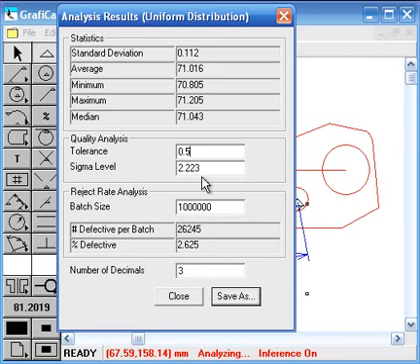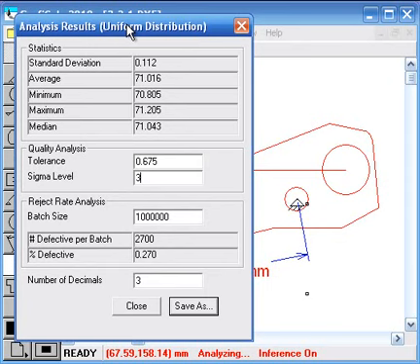He can either use a more expensive, more accurate manufacturing process to meet the tolerance goal as specified in the drawing, or he can simply enter the desired quality goal here, 3 sigma, and he can call the engineer who designed it, look, if you want really 0.25 plus minus tolerance, it's going to be an expensive part. But if you can loosen your tolerance to 0.3275 plus minus, we can make this part really cheap.